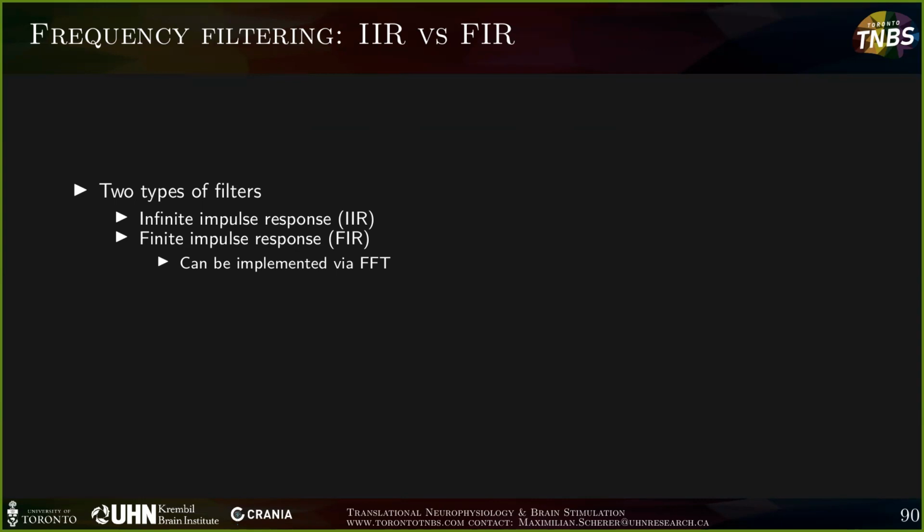On the other hand, if it's only provided with little data, the suppression that the IIR filter provides is not as strong. And another disadvantage is if you want to extend them to basically get super strong suppression factors, you're going to run into the issue that your IIR filter is going to get unstable and has all kind of weird hiccups that you're going to need at least a bachelor's in digital signal processing, something like that, to fully get rid of.